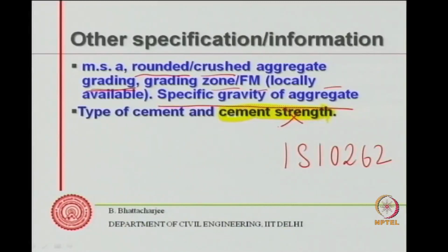Now type of cement is important, particularly related to durability. Well, this information is important in the sense that from the point of view of minimum cement content, this has got some importance, not really much, but what would be important for us to know, from our possibly past experience or from our record, is the kind of strength to water cement ratio relationship for concrete.